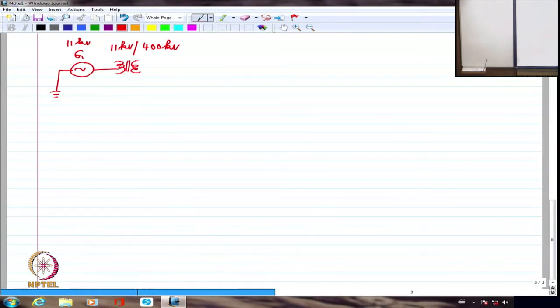So this has now brought down the current, and then from here it is going to get transmitted and distributed all over the country, for example. But when I distribute it or transmit it, these are 3 conductors. Please note all these are at least 3 conductors. And apart from that, I may have a neutral also, because if the generator is star connected, I may ground the neutral as well. So I will have 4 conductors coming out normally.